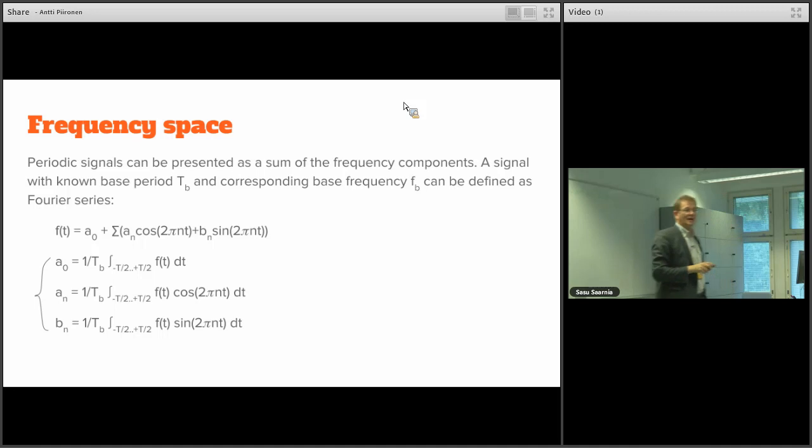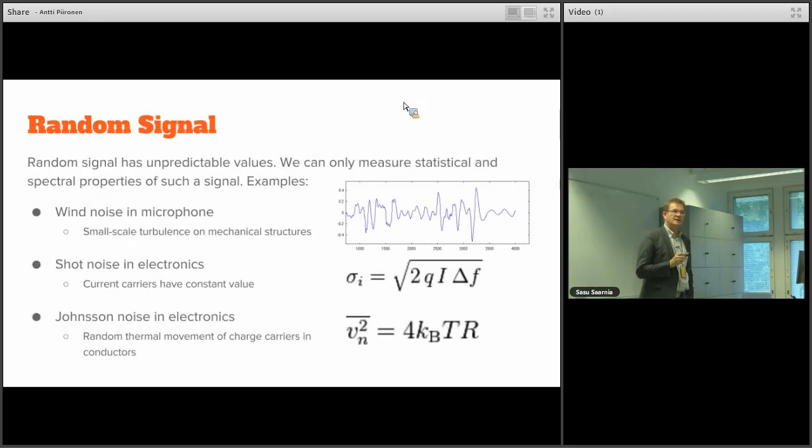By sampling a Fourier series, of course, you get basically the spectrum, and the spectrum components are A0, which holds the energy or power on the 0 hertz, which means DC offset. Okay, then An and Bn carry information in two phases, 90-degree orthogonal phases. Okay.